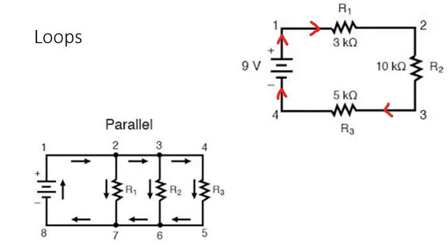So if we understand how the current flows, then I know that when the charges hit this side, or before they enter resistor 1, this is where they have more energy, and then they're going to give some of that energy to the resistor, where the resistor turns it into heat, and they're going to have less energy. Then it's going to be more energy, then it's going to be less energy, and for this resistor, more energy and less energy. So there it is. I'm assuming positive flow. I am kind of mapping the way the current flows, and then I put in my pluses and minuses accordingly. Where is it going to have more energy? Where is it going to have less?